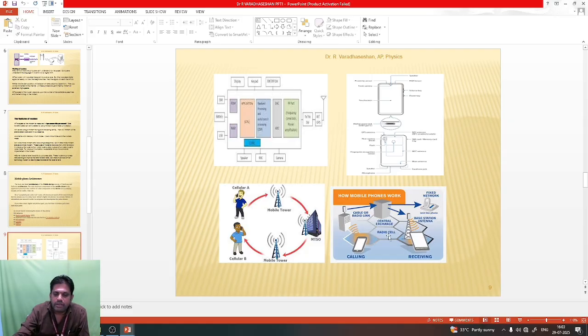Even though you are moving, your signal is transferred to the next hexagonal cell, the frequency is transmitted to another hexagonal cell, and this process is called handover. The technique is called handover. So you are talking here in this hexagonal cell, this base station will receive and give the information line to the central exchange by using two signals. One is input, one is output. So two frequencies. If you are moving to the nearest neighborhood hexagonal cell, what happens?